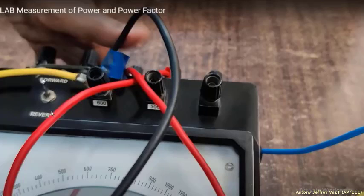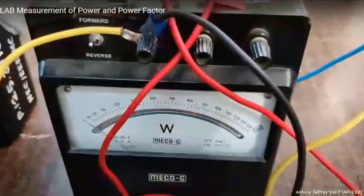Why this switch is present here is, if the wattmeter pointer goes from 0 to full scale, and if the wattmeter pointer goes to the negative terminal, I'll show you. Here it is. If the wattmeter pointer goes below 0, you need to make the switch in reverse.